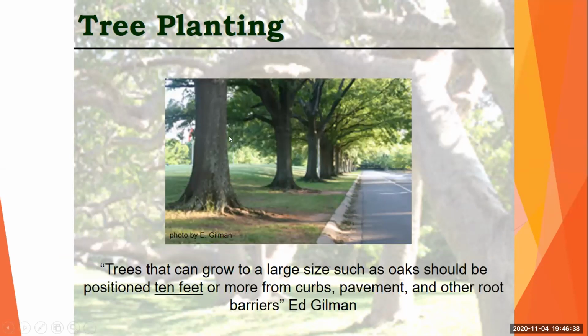So look at this. You have a lot of space here, a lot of soil volume, and big trees here, but you need to have some space between this and this. Otherwise you're going to cause a lot of problems to the street and the curb. So 10 feet at least from the trunk to the street.